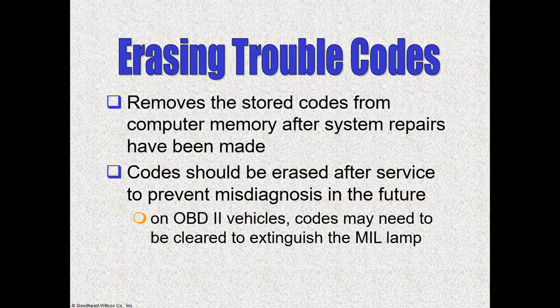Yes, so sometimes we solve the problem but never clear the code. Then the vehicle comes back with the check engine light on, not remembering that we never cleared the code, and we say the car has the same problem, when really and truly the problem is gone, but the code is just stored in memory.